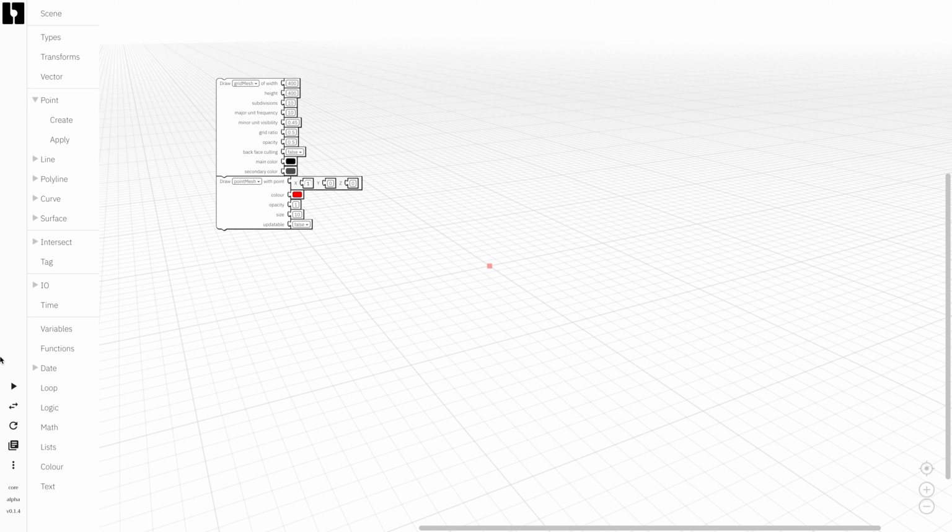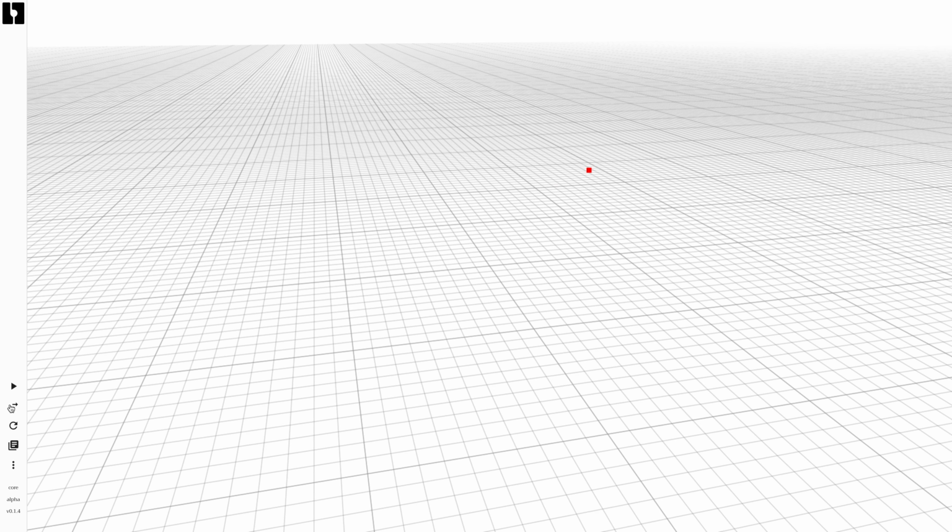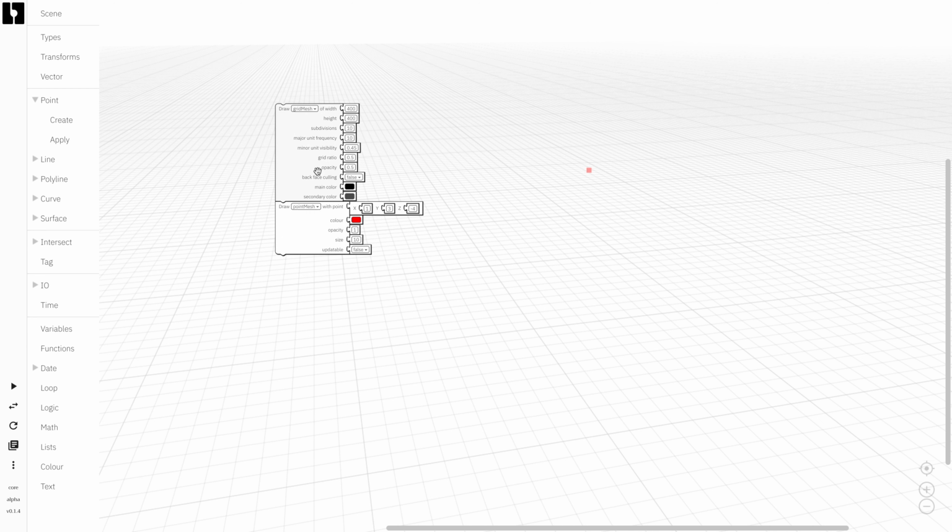Now you can begin playing with the coordinates, of course, to understand which axis is which. If I do x as 1, then it moves in that direction. If I'm saying that y is 3, then the point will move upwards by 3 units. BitByBit, by the way, is not metric, it doesn't have a real unit. You can figure out your own unit and just say if in your application 1 is 1 meter, then it's fine, but you have to keep track yourself of what that is. If you're saying that 1 is a centimeter, for BitByBit it's fine, no big deal. And z, of course, can also be negative. So -4, then the point will go somewhere else, and we see that it's not anymore in the center of the space, but still I suppose it's easy to understand how that works.